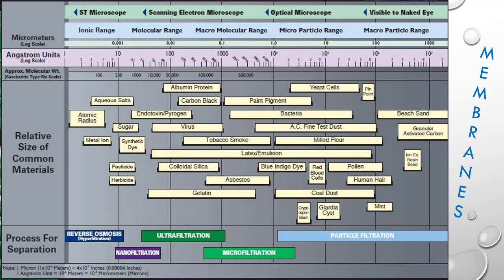Looking at this chart, you can see examples of common materials and their micron size. The right-hand side of the chart has the largest particles and largest in micron size, and the left has the smallest in micron size. According to this chart, we can see with our naked eye down to around 30, maybe 25 microns at best. After that, we will require microscopes. Sediment cartridges or mesh-type screen strainers that we use in daily water filtration are typically used down to just below 1 micron in size, and then we move into microfiltration cartridges for high levels of particulate reduction.